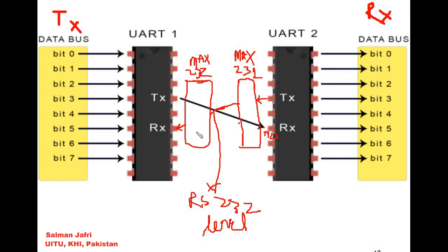The FTDI can be placed over here, and it would convert, so basically this would be the FTDI now instead of the UART, which would contain the serial protocol followed by the USB protocol. How this scenario would change would be made more clear by a diagram, right?